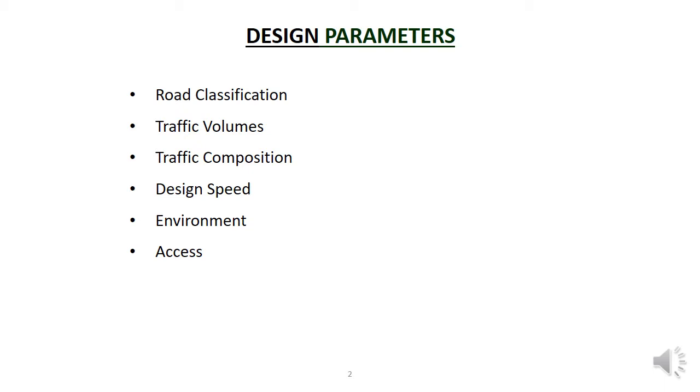The environment that the road is located in also varies. The area may be exposed to some storms, requiring better drainage, or it may be dry. The area may be low-lying and prone to flooding, in which case we need to raise the road surface, or it could be well drained. The underlying soil may be strong, or it could be weak and requires strengthening or a thicker pavement. The terrain may be mountainous and steep, requiring more bends and steeper grades, or it could be flat. Each of these environmental factors and more will influence how the road is designed.